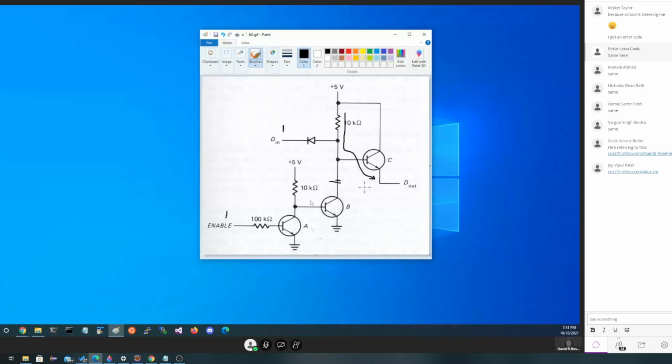Okay. Then if we did that, what we know is that even if we don't know what the value is right here, and the value right there, we know they're 0.7 different from each other, right? Would you agree with that? Yeah. Okay, so we got 0.7 different. That means the transistor is turned on.